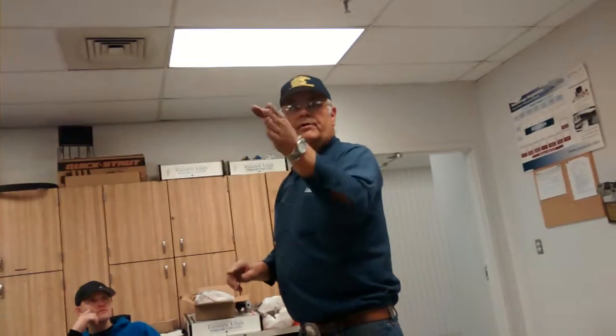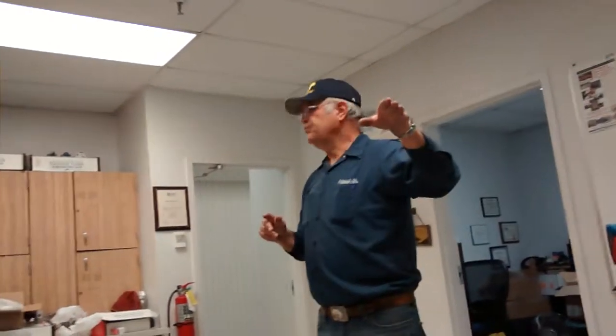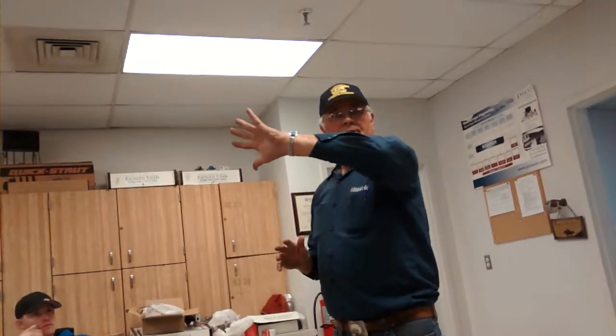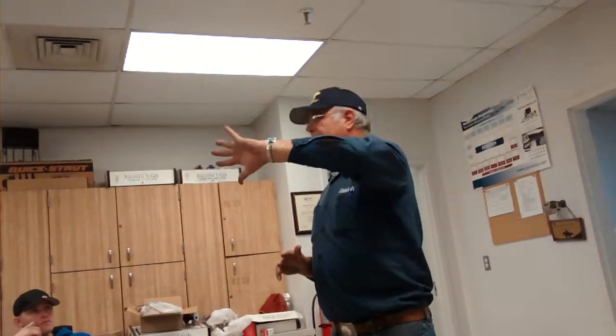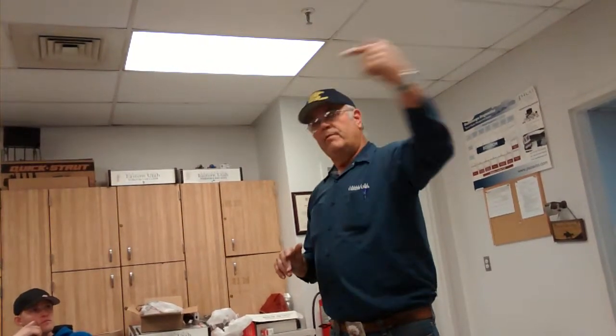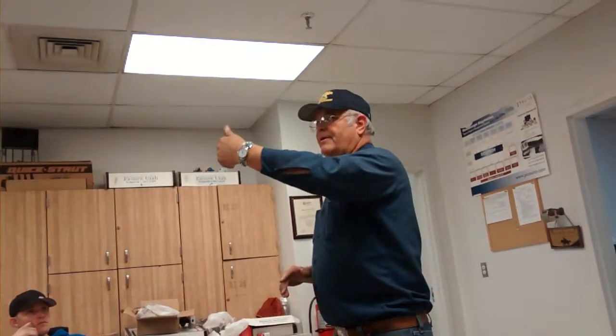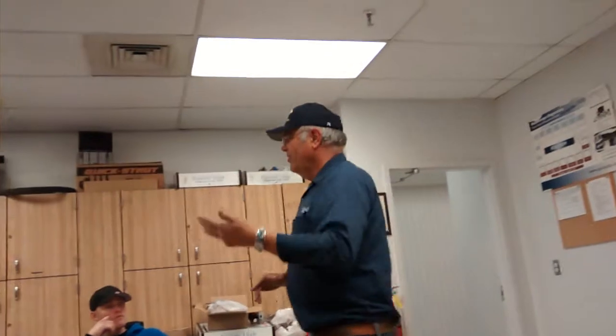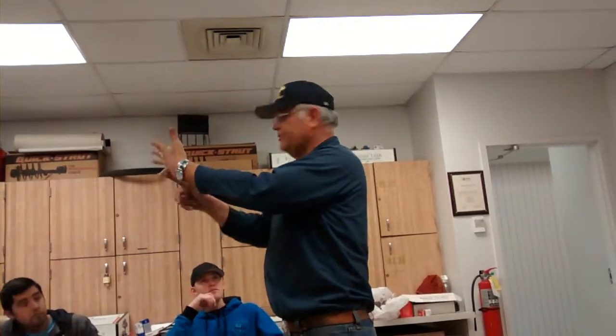That's kind of where we're at on yours, Corey, that I was telling you yesterday. We need to find out on his vehicle that he's working on, because we're just starting on live problems now. If you have something that's, say, 5 different things that are affected, part of the diagnosis is let's look what can affect those 5 things. If we have one power feed that feeds your brakes, your tail lights, your signal lights, your hazard lights, your dome light, and it's all fed by one source, and all these are affected, guess what?